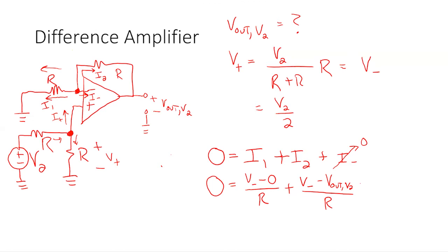I'm making the assumption that all the currents leave the node, and the implicit assumption in that is usually that the voltages go plus to minus like that. So I'm doing it differently than I would normally, the way I think most of you do it. Not everybody, but a lot of people do it that way.